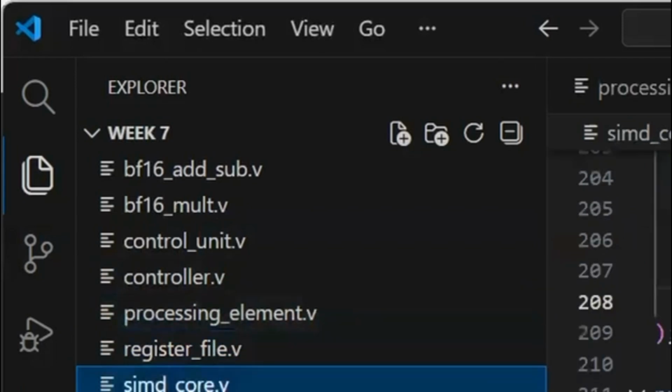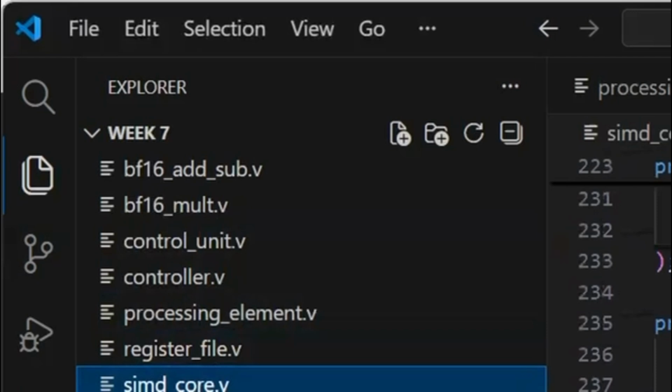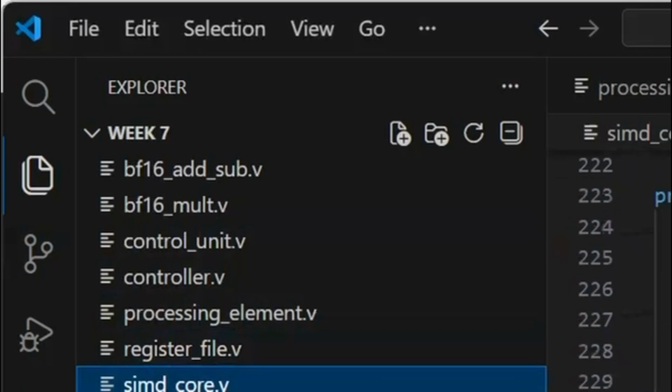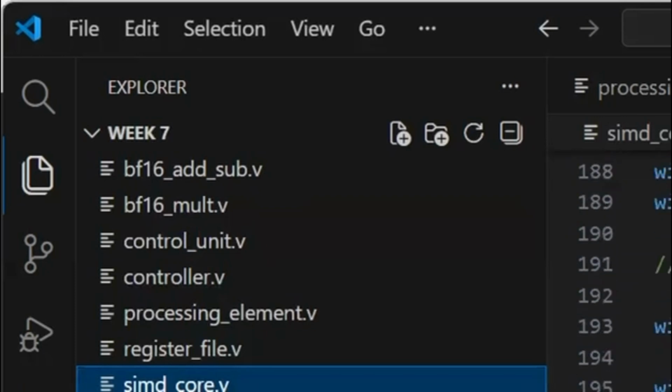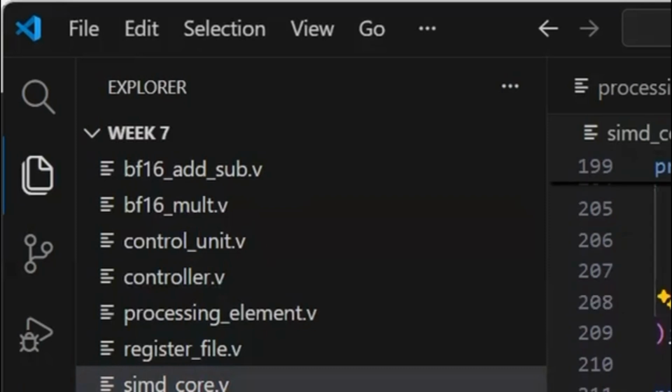And here in the assembly code, we have this after the data comes out from all of these. We have a single memory with 64 bits. We are storing the first 16 bits from processing element 0, the next 16 from processing element 1, and so on, like 4. I've declared a single 64-bit wire, and then write parts of it from different processing elements.